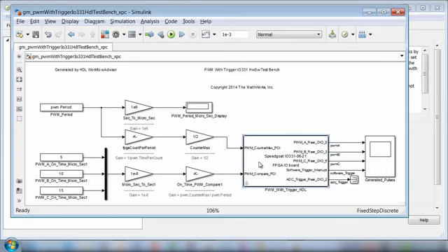So this stuff is all the same, but what's different is my PWM component subsystem has been replaced with what's called an FPGA interface module. This block contains all the information necessary to program the FPGA, and if there are any interfaces to the CPU, that would also be specified. In my case, I have these two ports. I'm sending two signals from the CPU down to the FPGA.